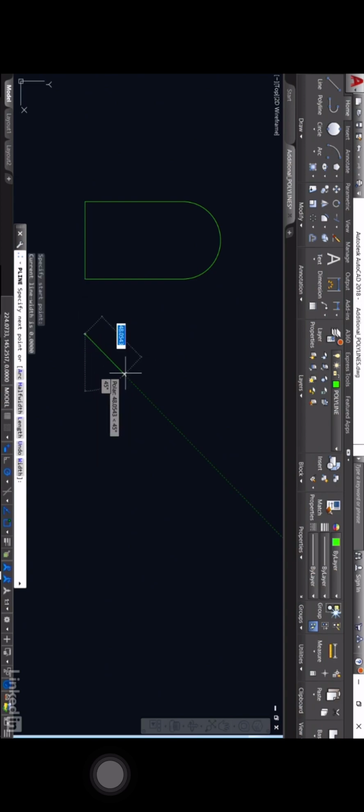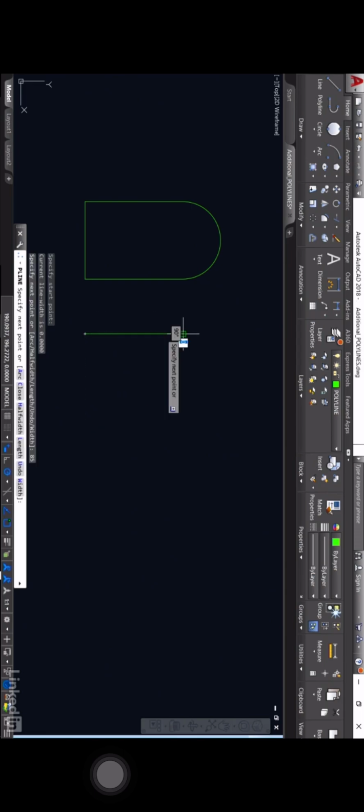Now what I can do here is utilize the polyline command and utilize the shortcut menu within the polyline command. Now the way that I'm going to do that is I'm going to use my polar tracking to go upwards like so, and I'm going to type in 85 and enter. So there's the first segment of my polyline, and as you can see, it's the same height as the vertical lines in the previous polyline where we used polyline edit.